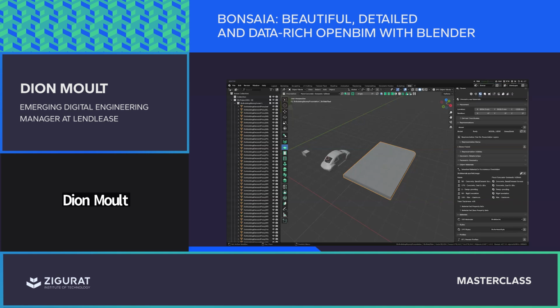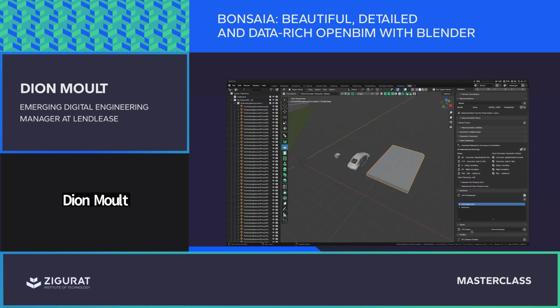And we can see there's actually 103 materials defined, which shows the quality of the model that people typically produce that they don't realize until they start digging into it and try to query it as a database. So we can see that there's probably not 103 materials used in this model. Similarly, we shouldn't actually have 192 styles or 800 types of profiles.